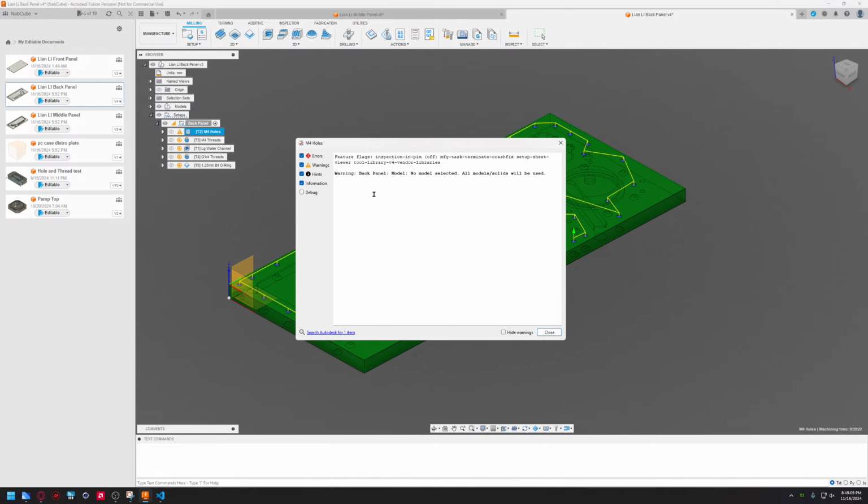As a result, the entire surface contained by the boundary might not be machined. See, it says inside. Boundary limits the center of the tool. It ensures that the entire surface inside the boundary is machined. Tool centered on boundary.